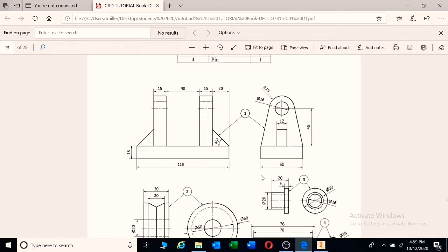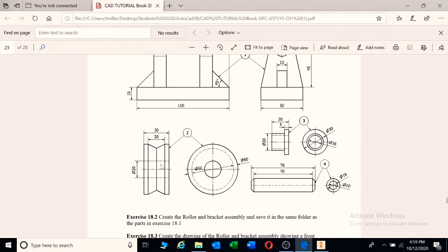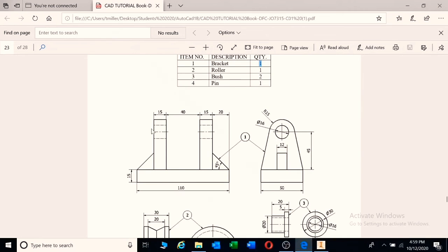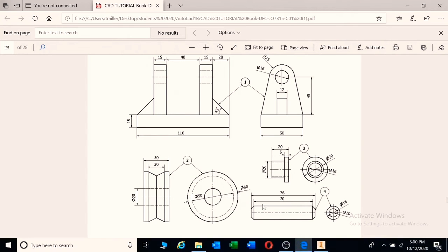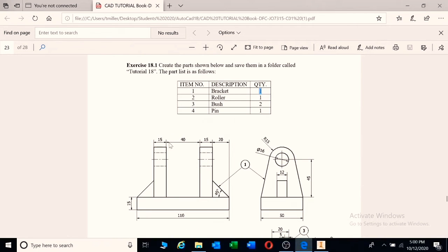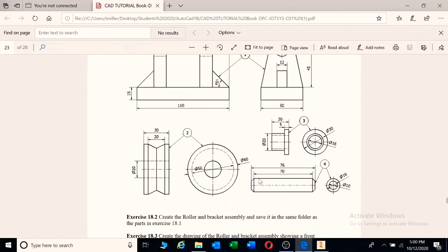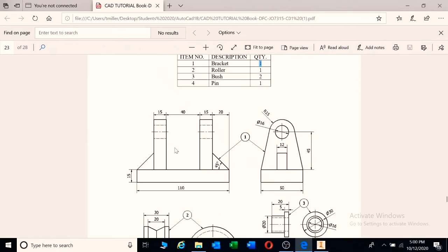And there we have another 16. So obviously this will go right through the center of this pulley, through the bushes, taking this whole contraption, where we will have 16 sticking out on the sides, fitting in there. So we have a length of 76 and a length there of 70. So taking this contraption, this will fit in the center, and then we have 40 in the center, 15 millimeters, 15, that gives you 70. In other words, it will take up that whole section of that shaft. So this is where the shaft will stop and the pulley with the bushes will sit in the center. And then we have the 3 millimeter chamfer sticking out on the side.